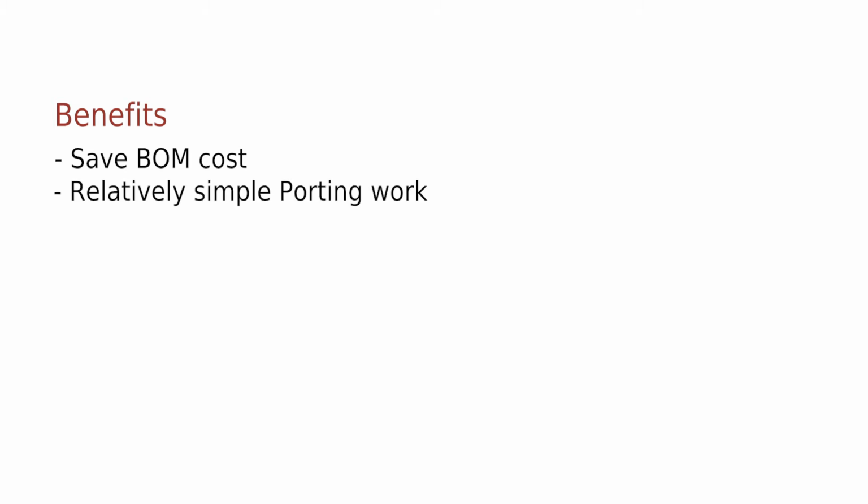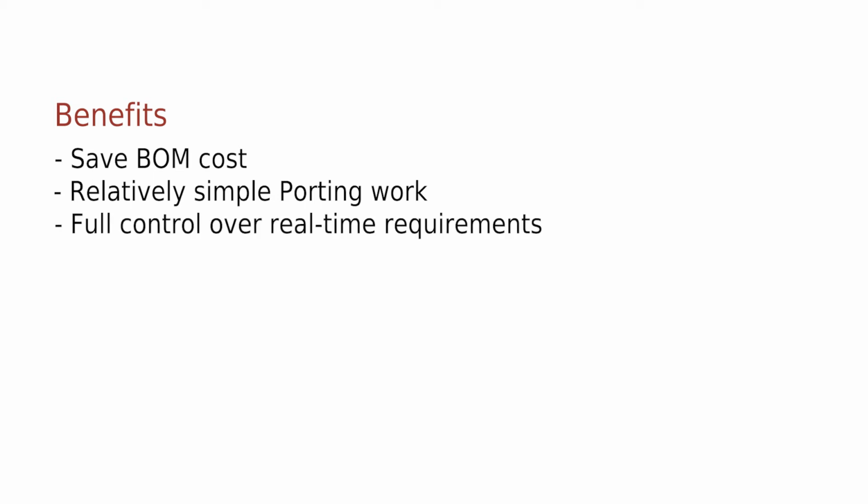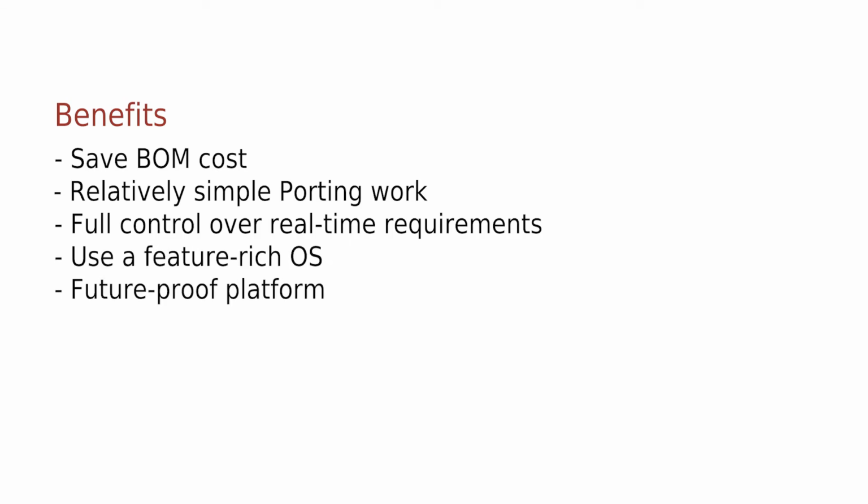Let's look at the pros and cons now. Remember that this is from the perspective to migrate a microcontroller-based design to an i.MX processor. There can be other perspectives as well. The benefits are: you can save bill of material cost because you get the Cortex-M core basically for free. The porting work of your existing application can be expected to be relatively simple. You keep full control over real-time requirements and you get separation between critical and non-critical tasks. You get access to a feature-rich OS. You create the future-proof platform.